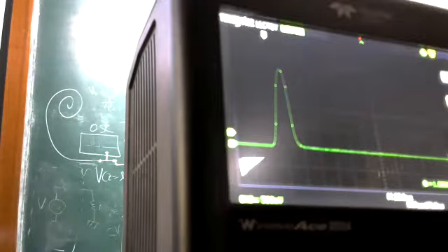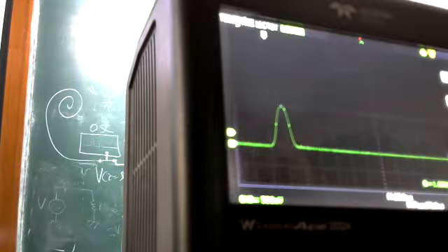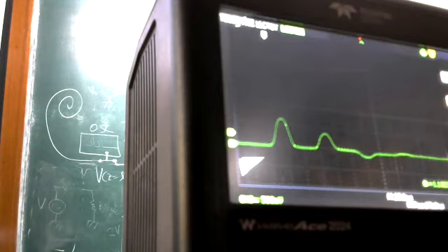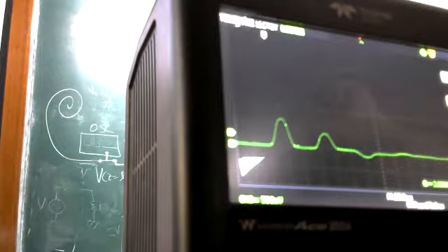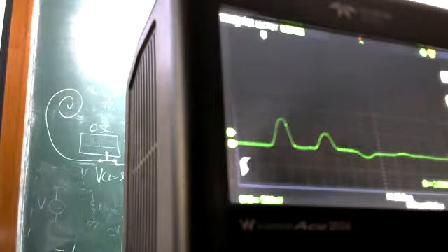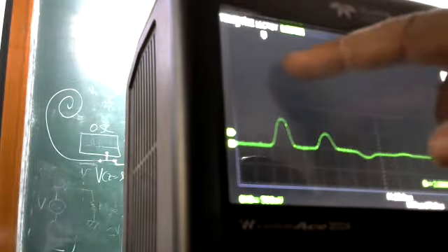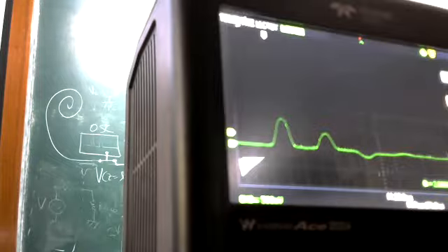Okay. Now I change the oscilloscope to 50 ohm. It drops by a factor of 2. Okay. I connect the cable. The first portion is now 1/3 of the old one, and it's 2/3 of the second one, right? Because earlier it was here at 4 divisions, 2 volts, then it became 1 volt, and this is like 0.66 volts, slightly lower because there's some losses and things like that.